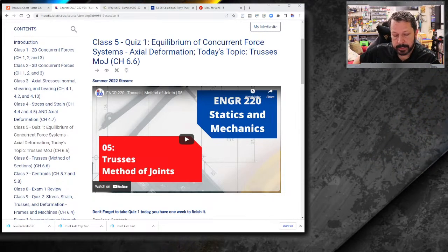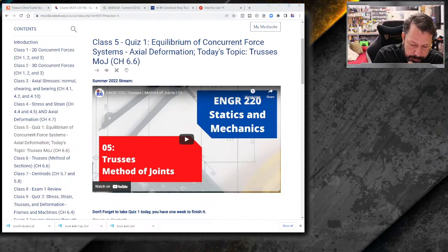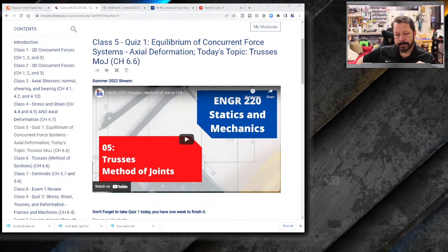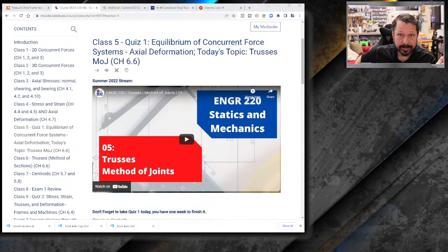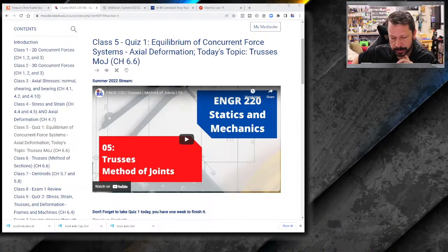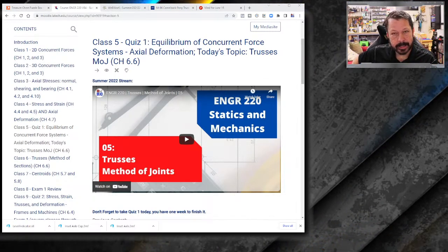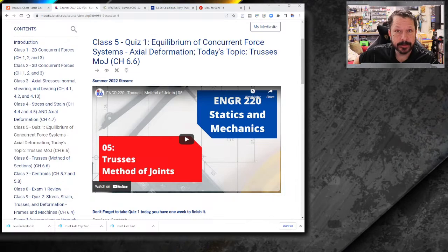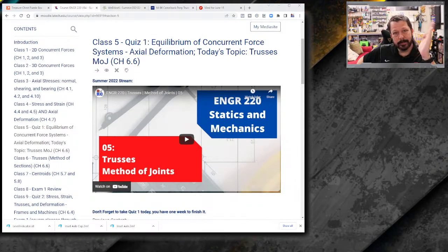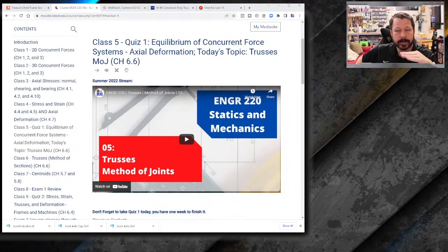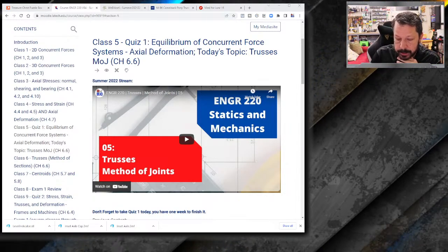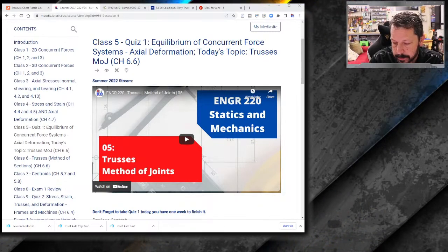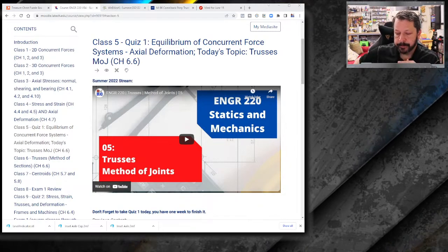Delta is how far that top left corner moved over, and L naught is the length of the side that corner is on. The interesting thing is that typically these are really small angles, at least in radians, because a shear strain isn't making a very large change. So we can typically say that gamma is more or less equal to just delta over L naught.